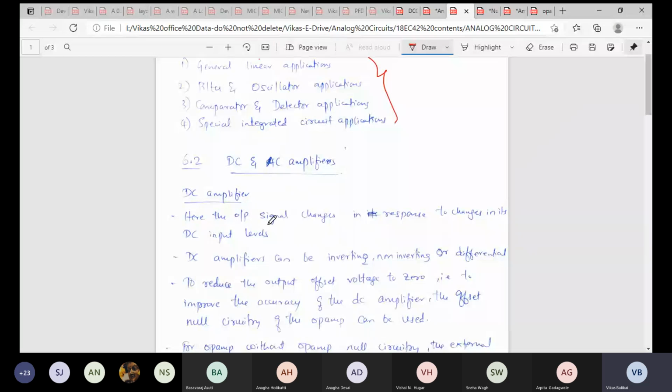Why? Because to ensure any transistor is behaving as an amplifier, first I should bias it in the proper region with the proper DC voltages. Remember this. For my transistor to work as an amplifier, I have to give it DC voltage and push it into a particular operating region. There the DC voltage is useful. Then for amplification, I give an AC input, and that AC input gets amplified. So any amplifier or transistor will need both AC as well as DC voltages.